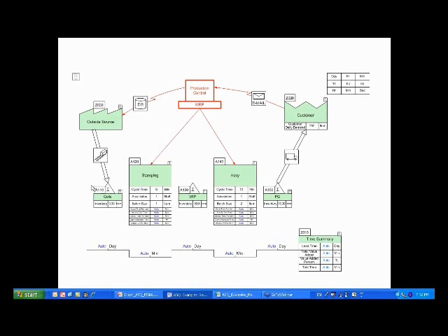So if I was to make a red scissor, the red scissor would have to wait for these 300 green ones to get depleted. Then it would have to go through a 6-minute cycle here, wait for the 500 to get depleted, etc. And then the red one would finally come out at the customer site. That total time that that red scissor took, having to wait in the first in, first out queues, that's what's known as the lead time. Now on this map, it'll actually be an addition of the non-value-added times, where it's having to wait for the inventory to get depleted, plus the value-added times where actually machines are working on it.